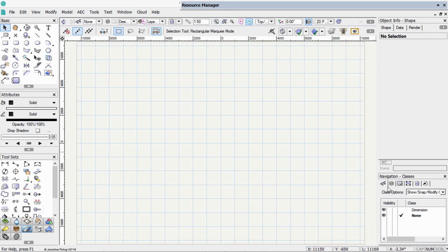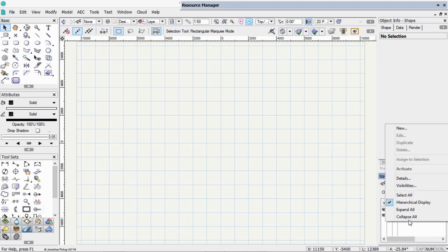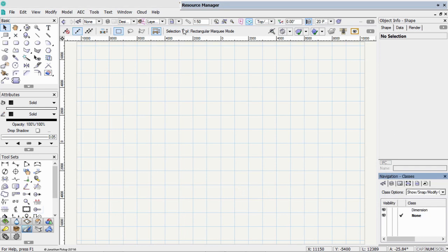In the previous exercises, we looked at design layers, sheet layers, and we looked at classes. Classes are going to be extremely useful, and you're going to need to create a lot of classes that suit your drawing technique. Now it might be that we can't create all the classes we need at the moment, but it's a good idea to try. So let's create some classes. Right click, let's create a new class.